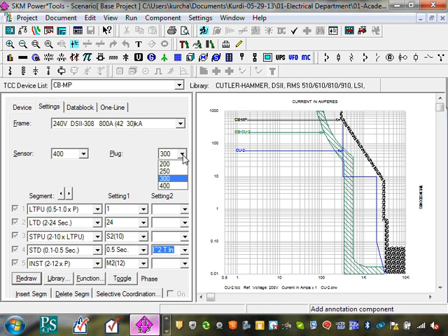So I take a frame of 800, sense at 400, because I don't care about all 800. I can plug it in, a little plug on the face of the circuit breaker. Here are my options: 200, 250, 300, and 400. That's an adjustable circuit breaker. Every time you pick one of these settings, you have a brand new circuit breaker. I have plugs from 200 all the way to 800. The maximum is 800. I can plug in and sense the CTs that you put on them. Now after I sense it here, I have a 300 amp circuit breaker.